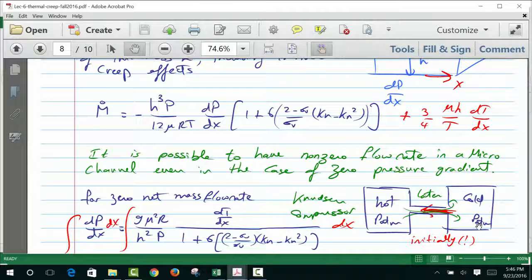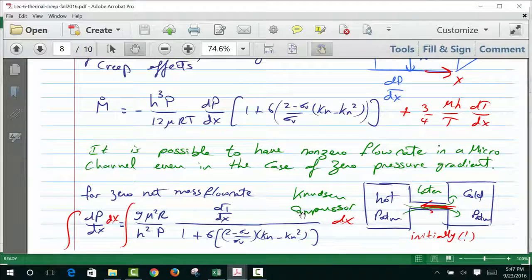So in this week's homework, in one of the problems, I'm giving you a pump. It's not driven by a thermal gradient, but by an electric field, which we will see after the break. I'm asking you for the maximum pressure that the pump can do. So let's see what is the maximum pressure that this thermal pump can do. You derive the equation for the flow rate like this. Here is a term from the pressure, here is a term from the temperature.